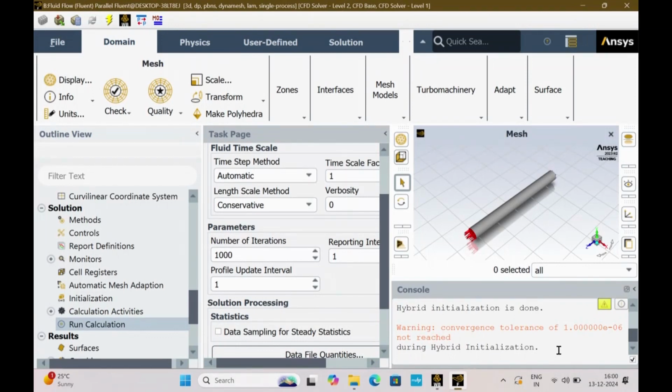For us it is not showing because we have taken something different. Okay, then it's good. So for this mesh, maybe, you will have to play with the mesh. For only the fluid flow part, it worked fine, but maybe for this part it will not. But the solution will anyhow converge, because the convergence criteria is very loose, 10 to the power minus 3. So you can visualize this, but quantitatively it will not be correct. So just close this after that.